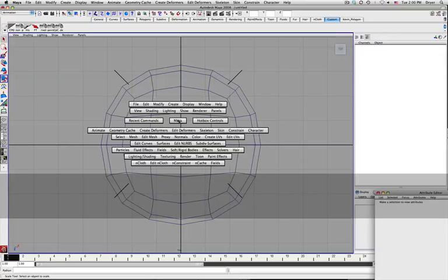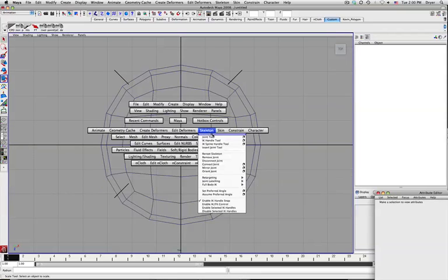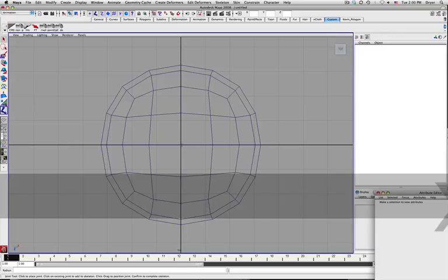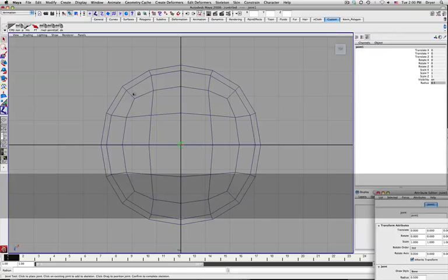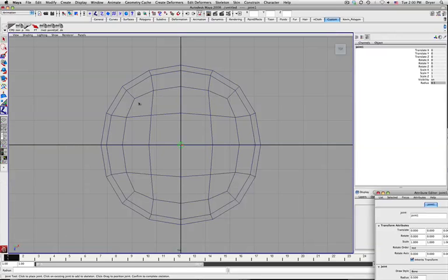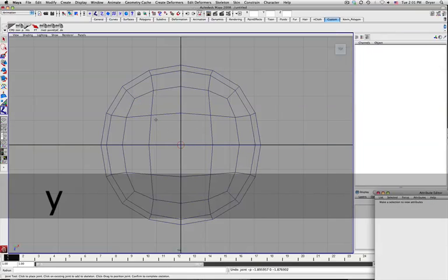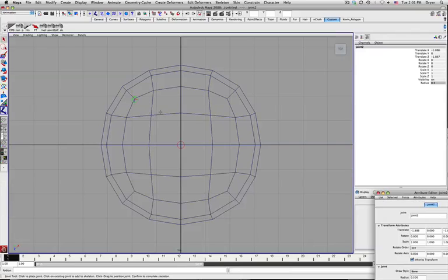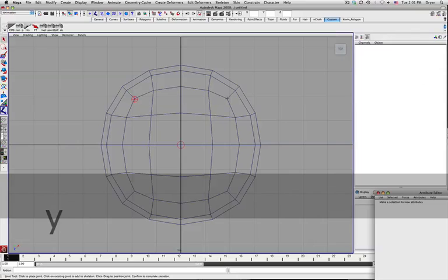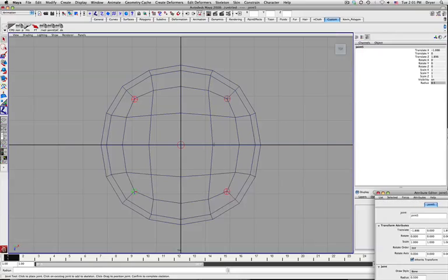So we're just going to create 5 joints for this. So go to skeleton, joint tool. Just going to put one right in the middle of the world here. Then I'm going to put one on each of these sort of 4 quadrants. Oops. I just made a mistake. You want to make a joint and then hit the Y tool, because it ends that chain and just activates the joint again, so you don't get a bone between the joints. Remember, we're just using these as little placeholders, so I'm hitting Y to finish the chain and start the tool again, so I get 5 joints that way.